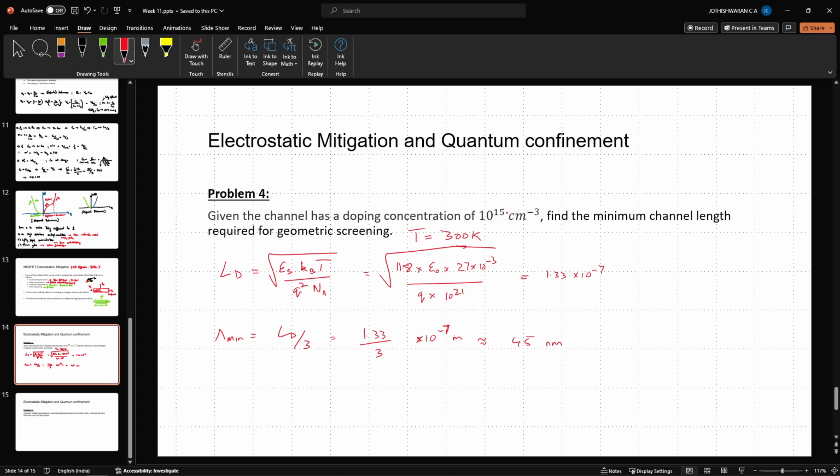If I use 10 to the power 18, that was actually a bit high, to the point of a degenerate doping. Let us say I took 10 to the power 17, 10 times less than that. Then it will be 1/10 of this, and I would need a channel length of 4.5 nanometers, which is around our current standards. So we can even have moderately high doping, like 10 to the power 16, which is good enough non-degenerate doping.